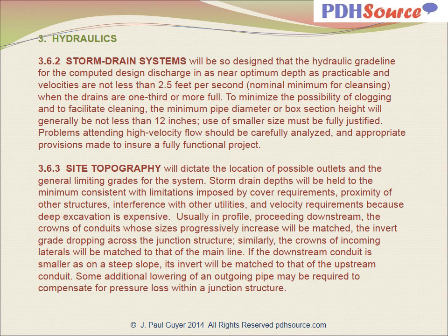Site topography will dictate the location of possible outlets and the general limiting grades for the system. Storm drain depths will be held to the minimum consistent with limitations imposed by cover requirements, proximity of other structures, interference with other utilities, and velocity requirements because deep excavation is expensive.